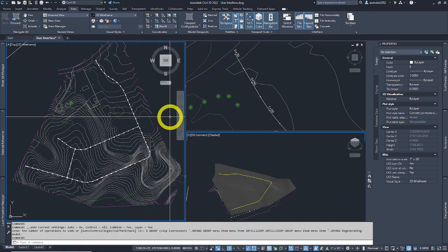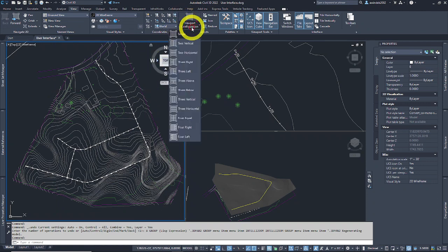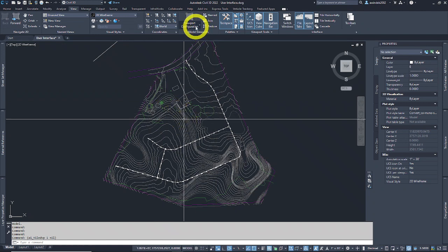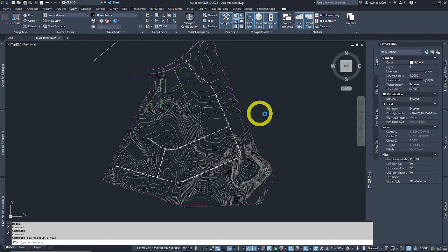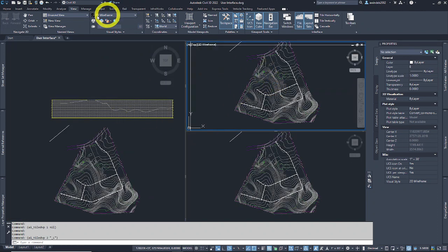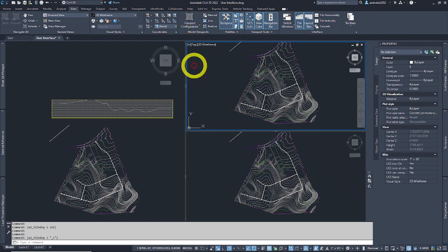So by left clicking in that viewport within my model space, I'm activated in that view. Now if I go to single, it'll collect this view. But if I go back to viewport 3 left, it'll copy this view 3 times. There's other ways I showed you in class how to save a view here through named views, so you can save that 3D view. Let's not worry about that right now. It's single view for now.